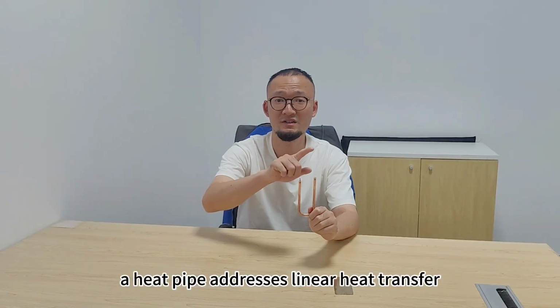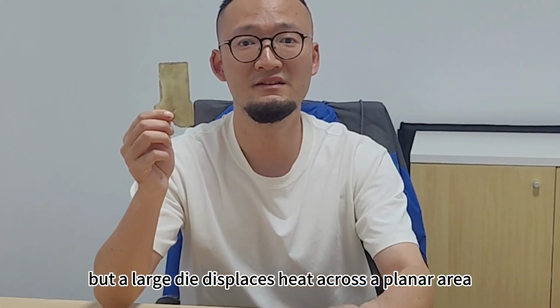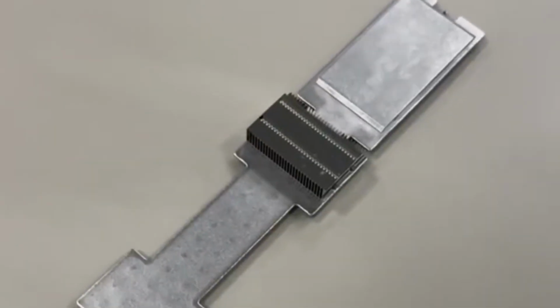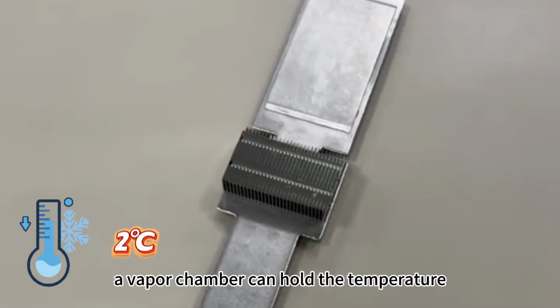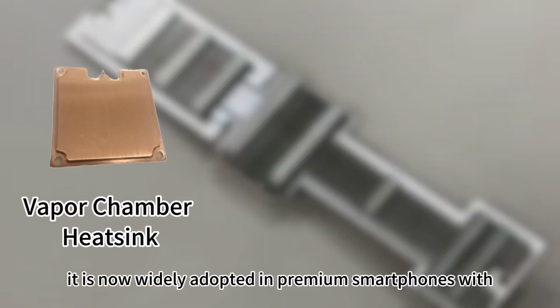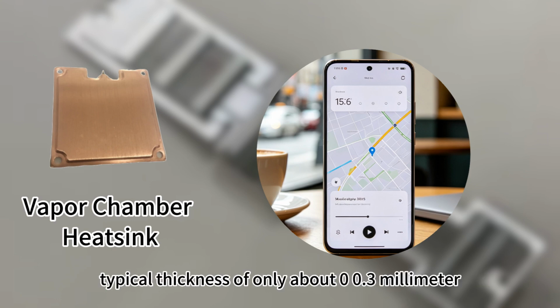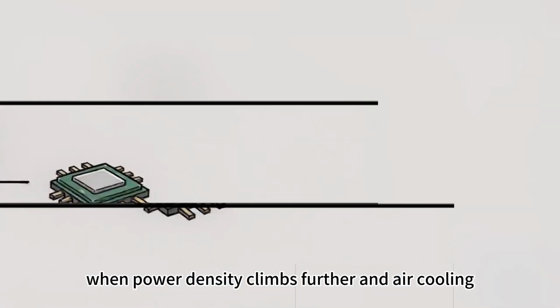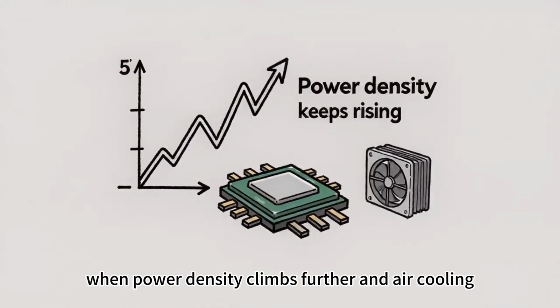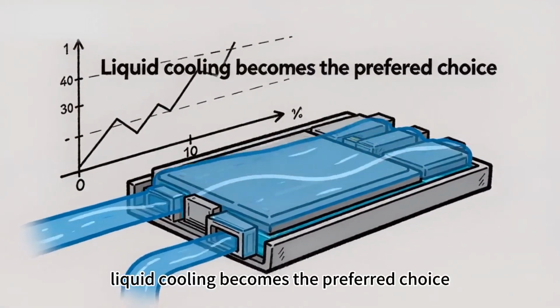A heat pipe addresses linear heat transfer, but a large die dissipates heat across a planar area. For large dies, a vapor chamber can hold the temperature difference across the chip within 2 degrees. It is now widely adopted in premium smartphones, with typical thickness of only about 0.3 mm. When power density climbs further and air cooling and passive solutions approach their limits, liquid cooling becomes the preferred choice.